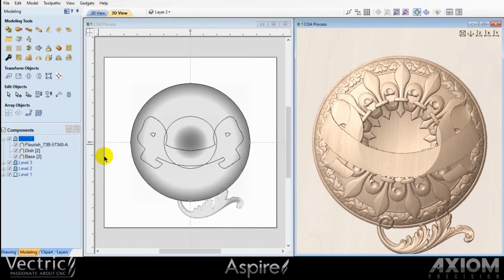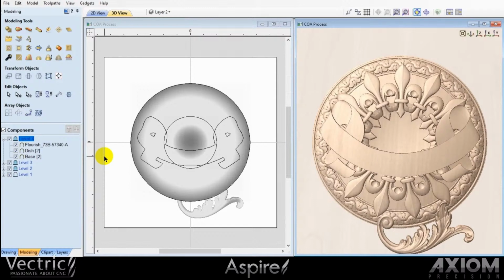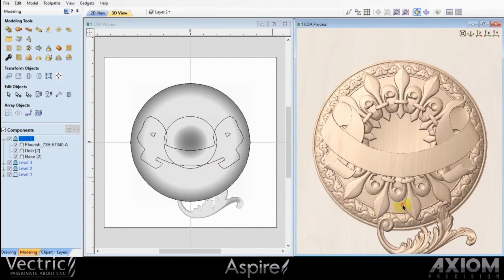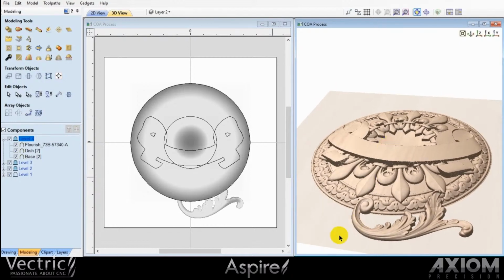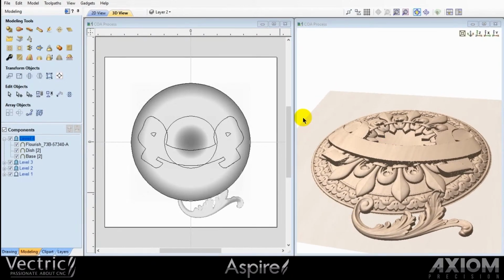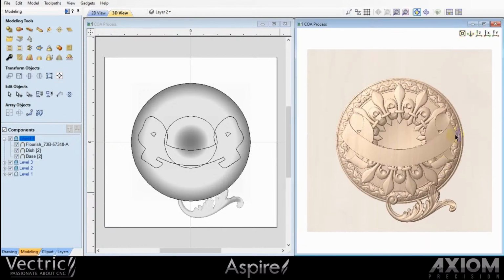Now, to get rid of that tail on the left-hand side, I like the right, not thrilled with the left. Here's a suggestion. If you right-click on the level 4, you can choose mirror mode.